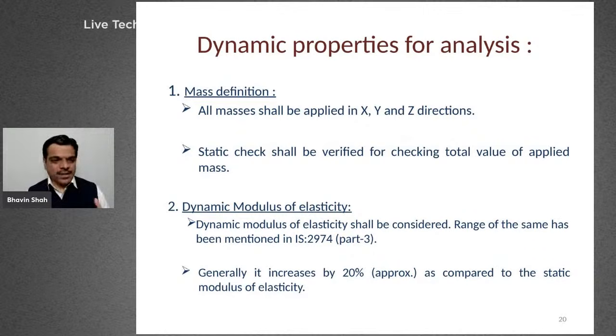Because I've seen in a number of problems that, out of enthusiasm, a very high-end model is created, and then all kinds of dynamic analysis are performed, and then at the end, after performing a few iterations for 4 or 5 days, it was observed that the static check itself is not correct. That means mass definition was not correct, and there was a lot of repetition. So always, that's a very important point which I am suggesting, that static check shall be done before we move for the further dynamic analysis.